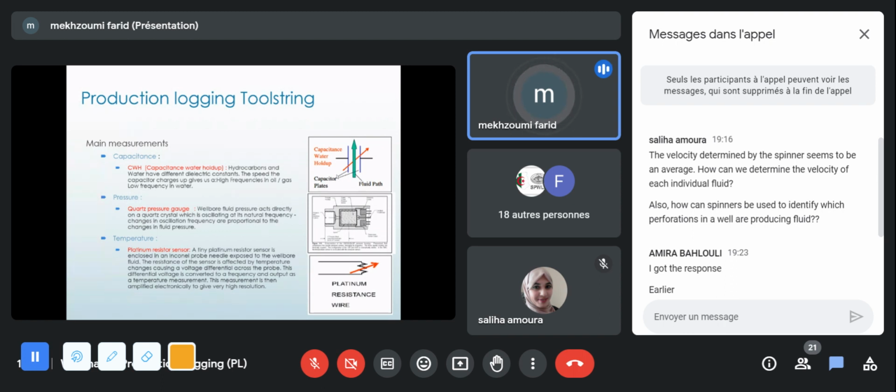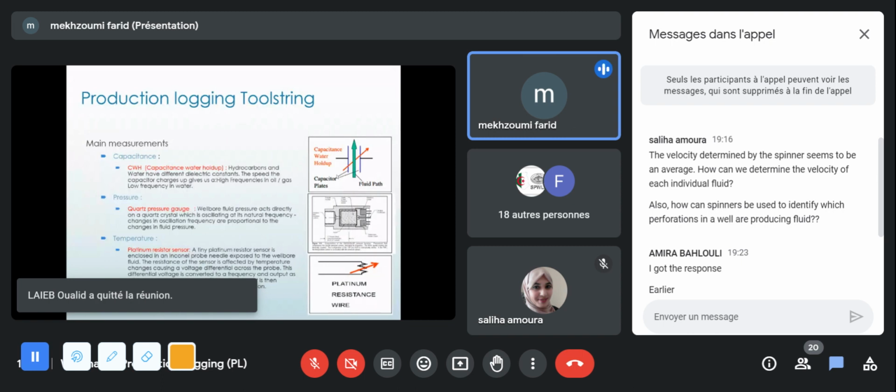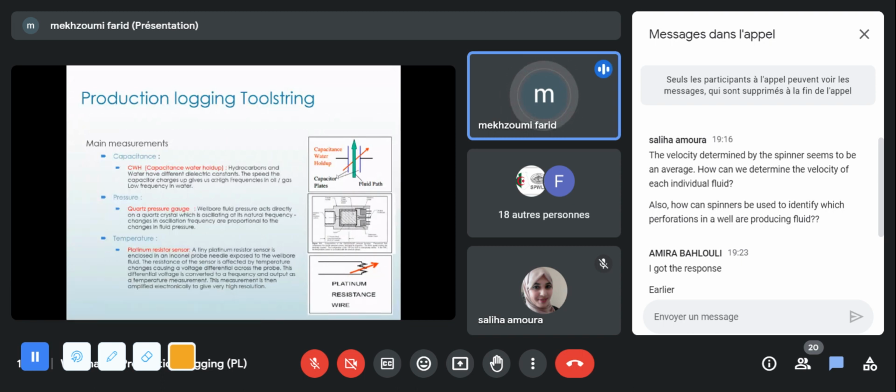If we talk about the horizontal well, the good thing about a horizontal well is that we have stratified flow. The slippage velocity is zero because each phase is flowing by itself. And I also have sensors like the spinner, measuring the flow directly. So with the multi-array tool, I can get the velocity of the oil phase directly. Okay, good.